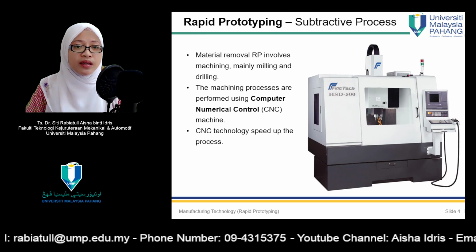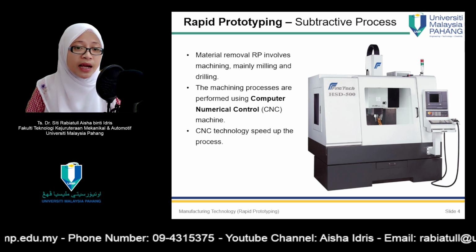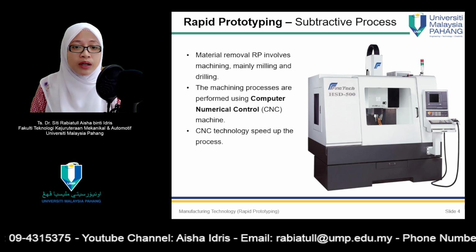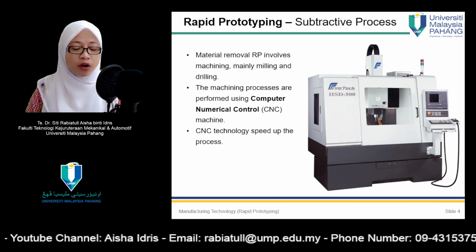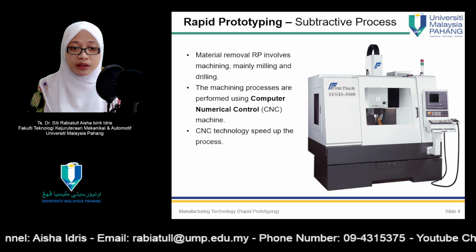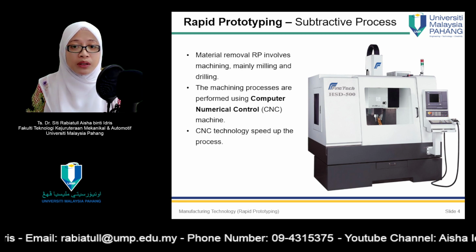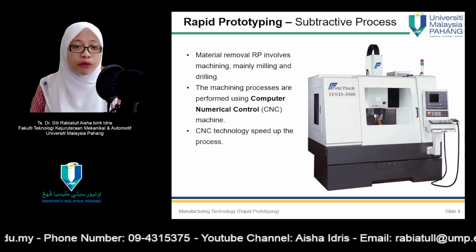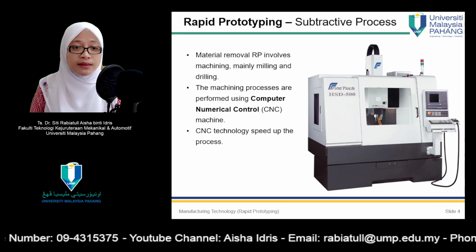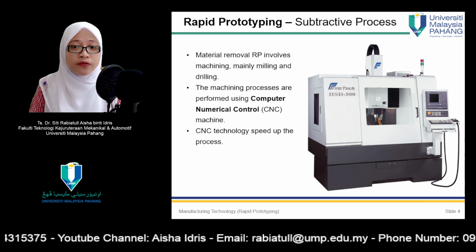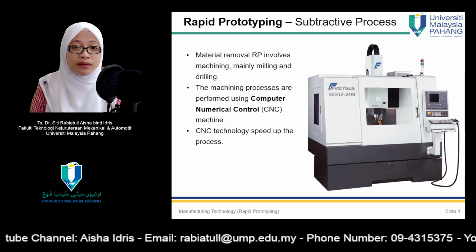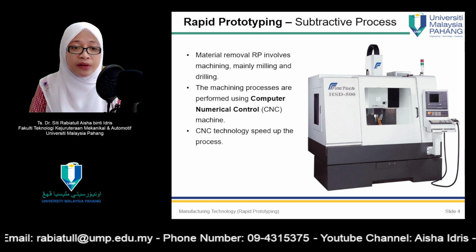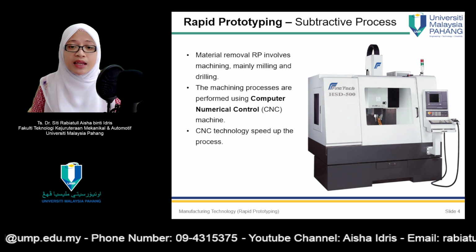The special need that motivates the variety of RP technologies arises because product designers would like to have a physical model of a new part or product design rather than a computer model or line drawing. The creation of a prototype is an integral step in the design procedure. A virtual prototype, which is a computer model of the part design on the CAD system, may not be adequate for the designer to visualize the part. It certainly is not sufficient to conduct real physical tests on the part, although it is possible to perform simulated tests by finite element analysis or other methods. Using one of the available RP technologies, a solid physical part can be created in a relatively short time. The designer can therefore visually examine and physically feel the part and begin to perform tests and experiments to assess its merits and shortcomings.